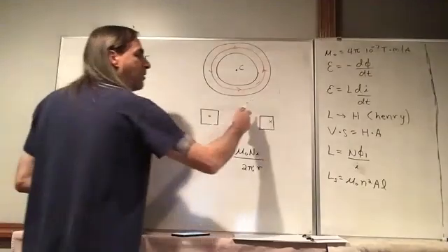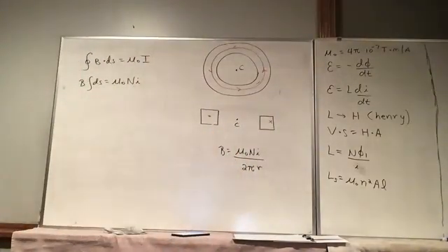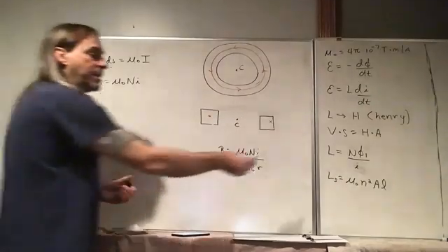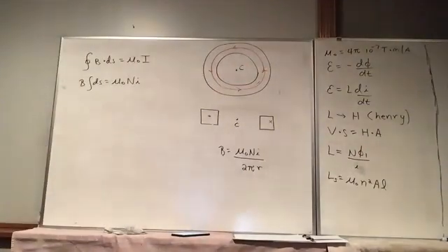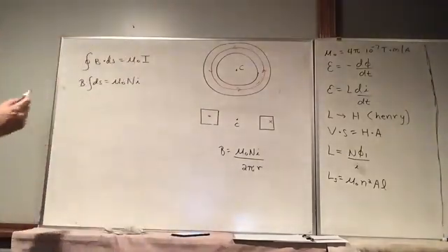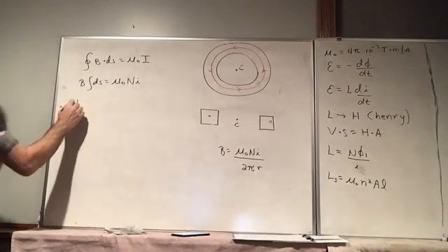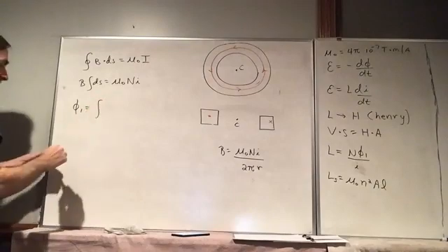And now the magnetic field is not constant inside this cross section. So again, we're going to use the same formula to find the inductance. In this case, the flux, phi1, is the flux through a single cross section, and so we have to find out what that is. To find the flux, we have the integral of B dot dA.